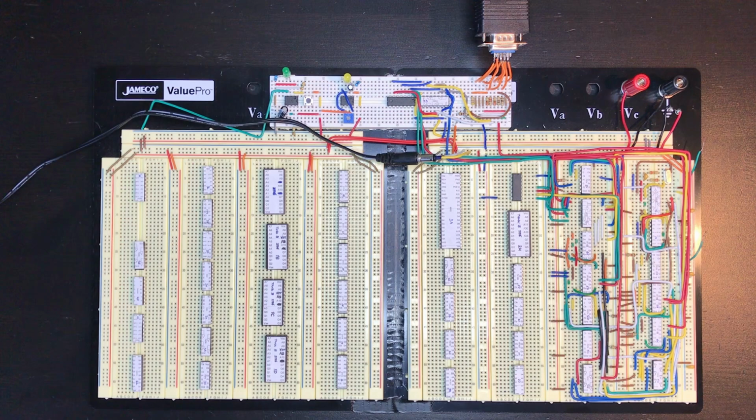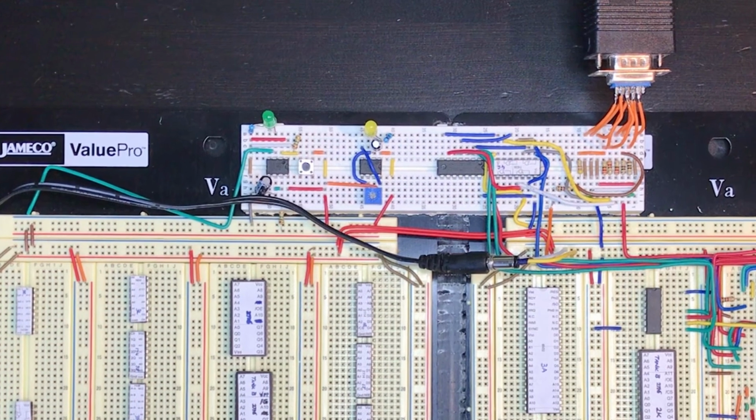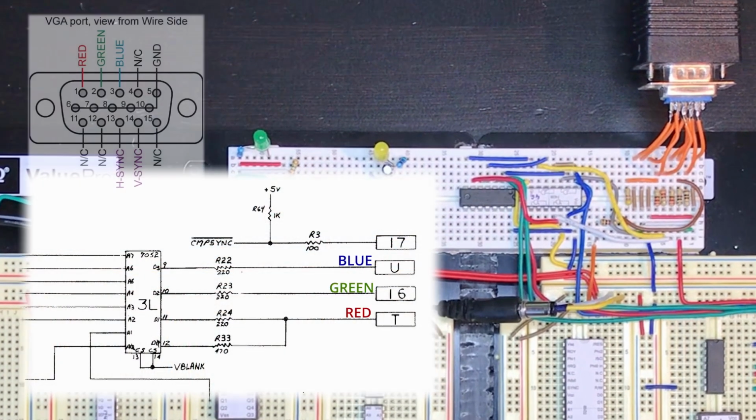Now let's remember I'm recreating the actual arcade system board here, so we need to use a regular CRT display. To get a picture on my CRT, I need to add the red, green and blue outputs through a connector, and I'm using a VGA port to carry the RGB signal and the C-Sync. My PVM monitor expects the C-Sync to be on the H-Sync pin, and the V-Sync pin is not actually being used. I've included a view of the pinout that's shown on the wire side, or the side that goes into my breadboard. You can see from the schematic that each color signal comes from a chip through a 220 ohm resistor and connects to the monitor.